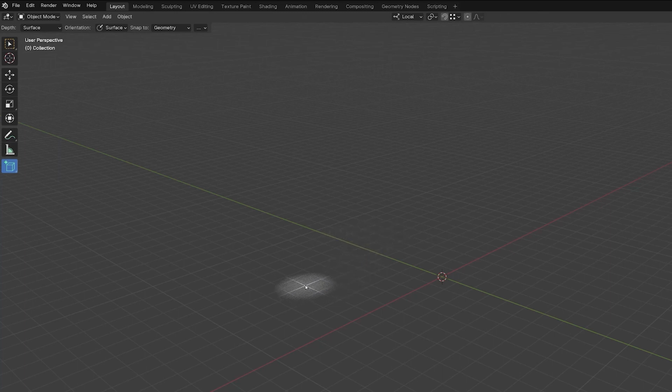Once we've selected a position, pressing down on the left mouse button marks one corner of the cube we are about to create. Dragging the pointer adjusts the size of the base, which shows in a wireframe style. And when we finally release the mouse button, this marks the diagonally opposite corner from our starting position, finalizing the area of the cube's base.